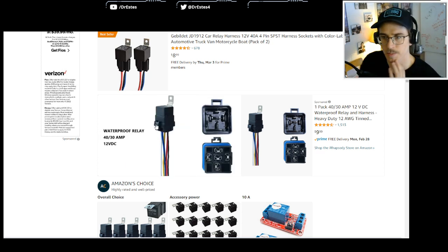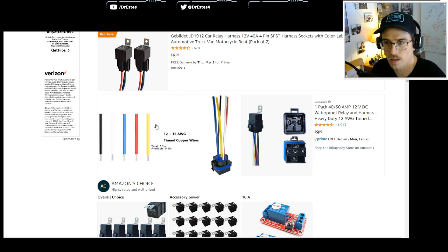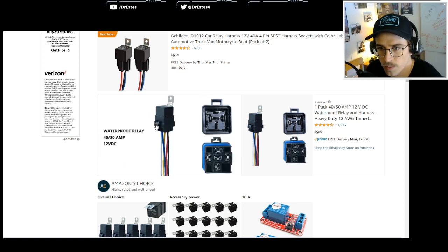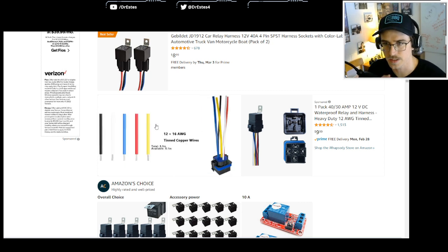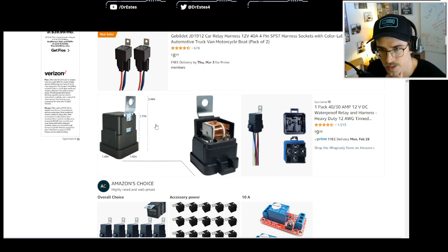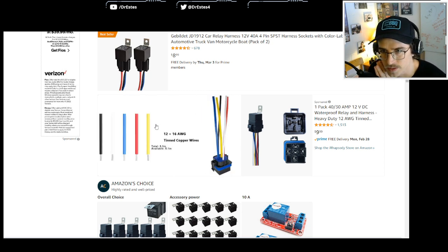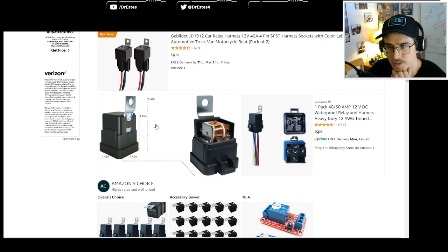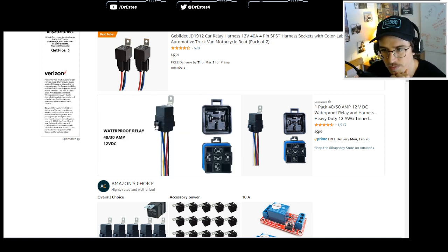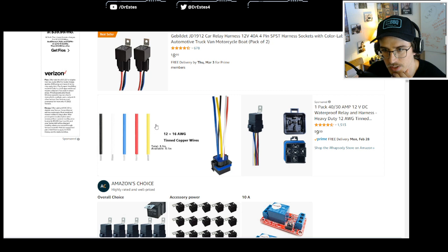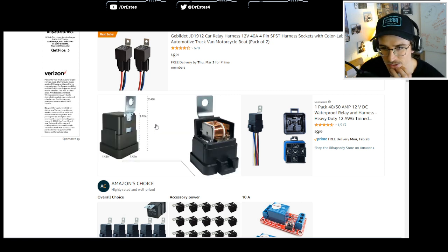Lego Logan says, keep in mind that you want the transistor in its saturated state. That is, enough current through the base that the transistor starts to act like a switch, not a linear amplifier. Take a look at the data sheet and they will have a graph that tells you what base current you need for what collector current under saturation. So no math, just a fancy lookup table.